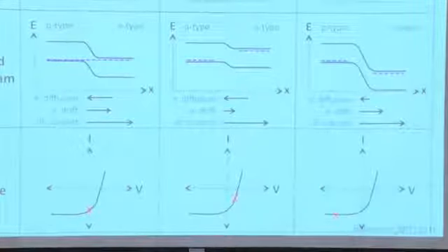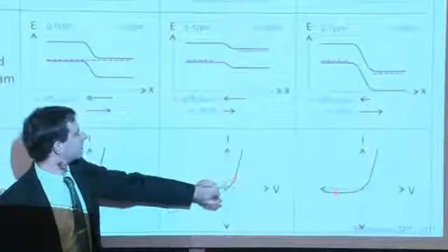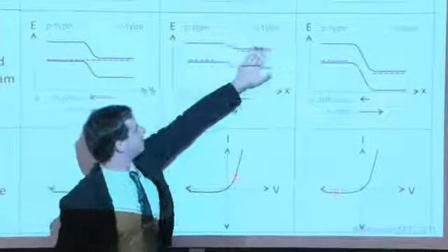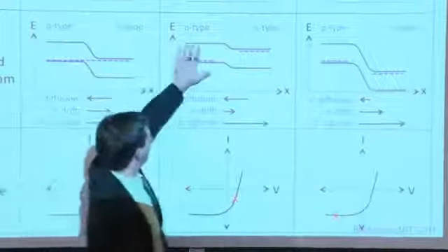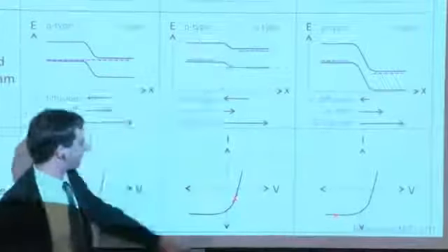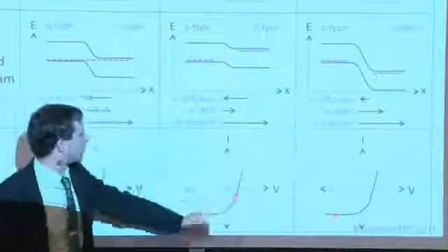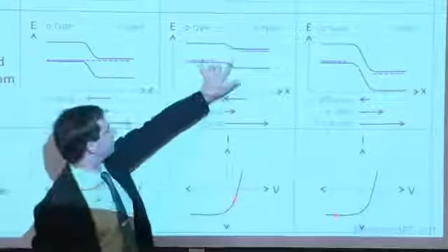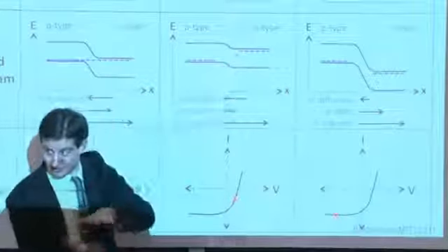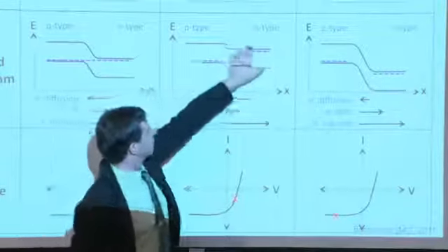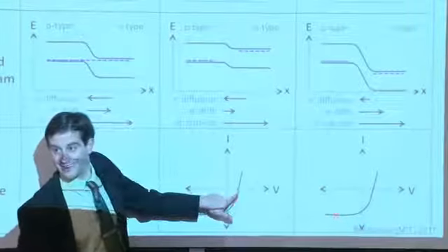That's pretty cool. That wasn't the case when we had the device in the dark. Here, in forward bias conditions, we're actually forcing carriers from the N-type material into the P-type material, right? But under illumination, now we have all of our carriers traveling from the P-type into the N-type. What's varying is the potential that the carriers have, and of course the total amount of current. As you forward bias more and more and more, this downhill slope here decreases, right? So there's less of a driving force for the carriers to be going from the P-type to the N-type, and that's why the current approaches zero.